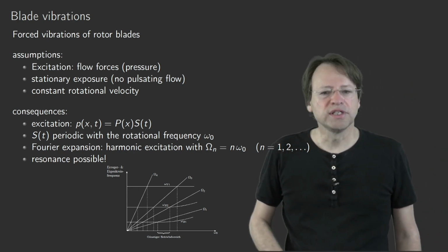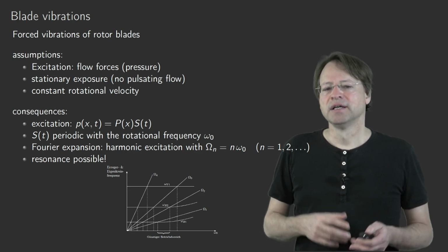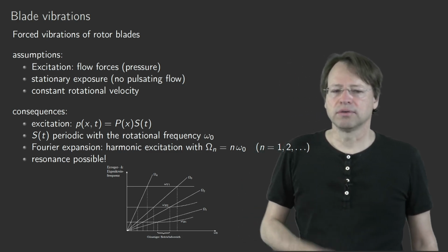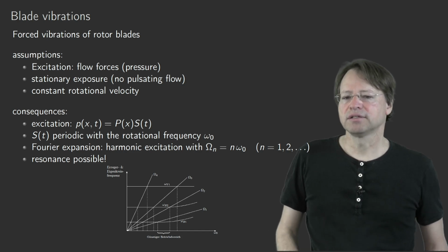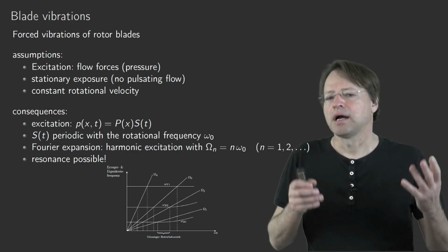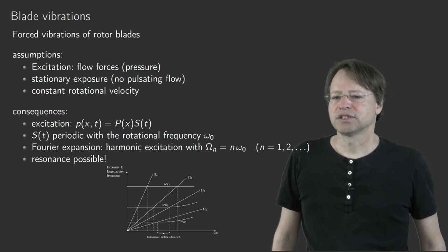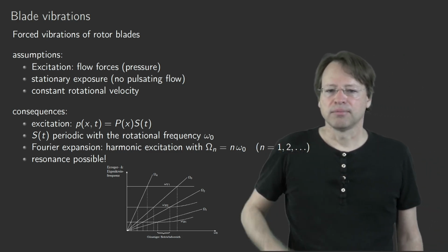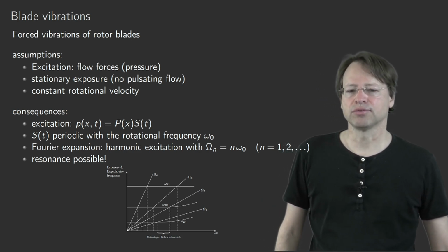And now the question is to design the blade, that is, to make sure that you have a safe design with respect to fatigue of that blade, and of course with respect to rupture. This has to take into account the situation that there might be resonance with respect to some higher harmonic perhaps. We will also look at the static case, at the static excitation, and then of course at the harmonic excitation, and take resonance into account. That's a little bit what we have to do.